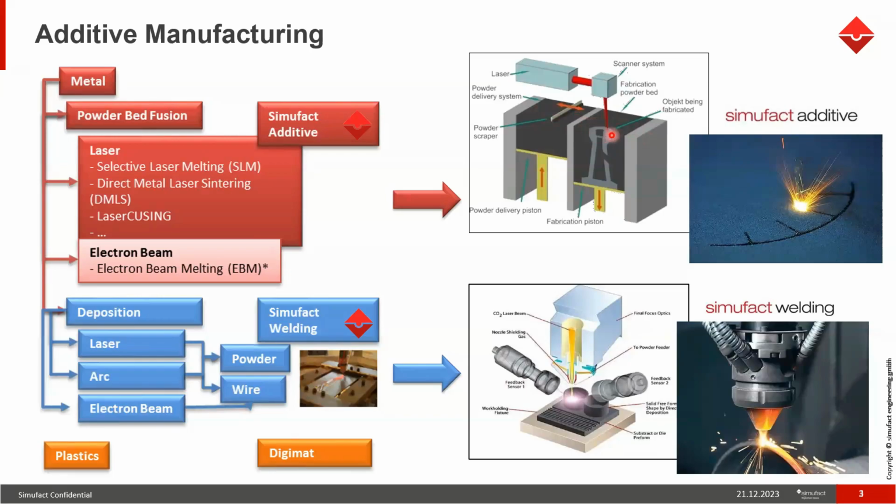Then the powder will be laid on this chamber, and the laser will come and melt a particular portion, so that the part gets melted there. Subsequently, another layer of powder will be supplied by the recoater onto this location. As the laser melts this region, a layer will be melted on a particular zone.